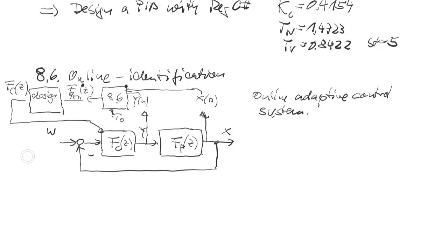So in my simulation I show you a system which has a desired value which goes up and down, say each second. So this is a rectangular signal, and the output should follow as fast as possible, and then in my simulation I can change these parameters, and you will see this automatically changes the model parameters and the controller parameters, and automatically the control loop is adapted to this change. So, depending on the controller type, you see this is chapter 9.